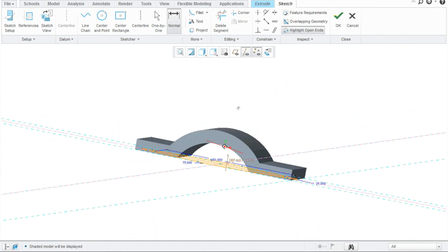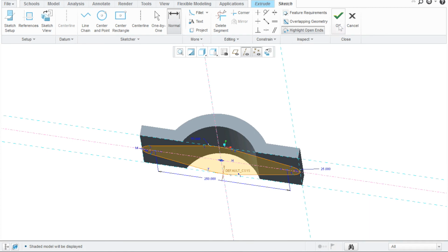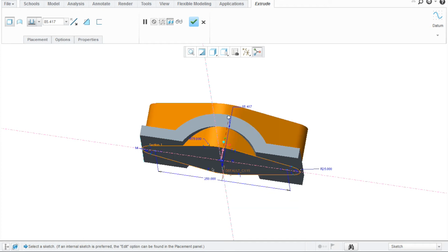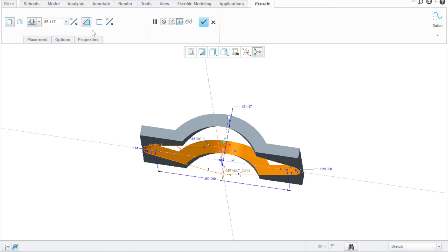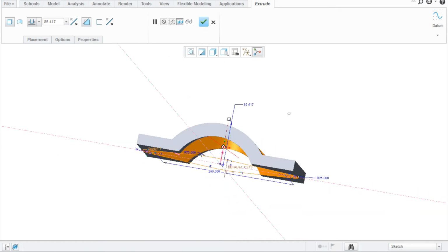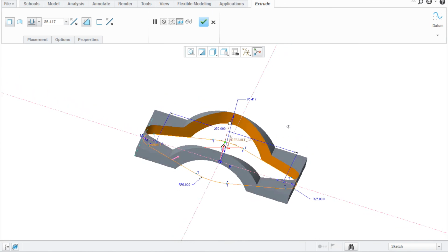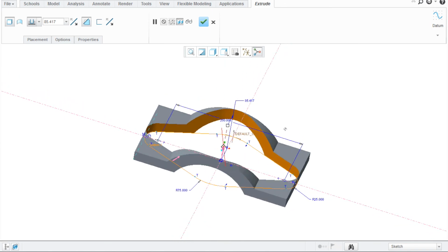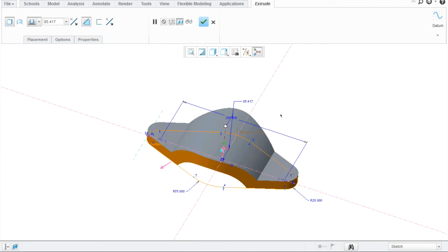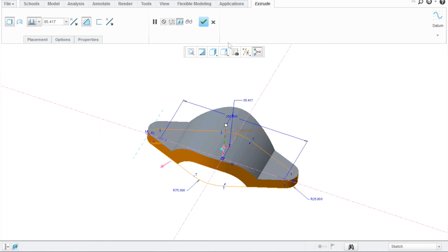I'm right here, and I'm going to say extrude. We're going to reverse the arrow, and then we use the cut. This is the cut, remove material. Do not worry that it poked a hole through here. There's a big hole in there. Just look for this arrow. See that arrow? Click on the arrow to reverse it. Now it's exactly what we wanted, and then we say okay.